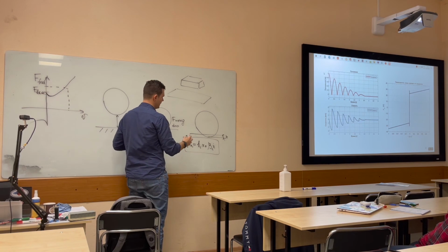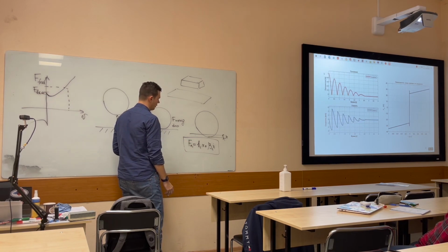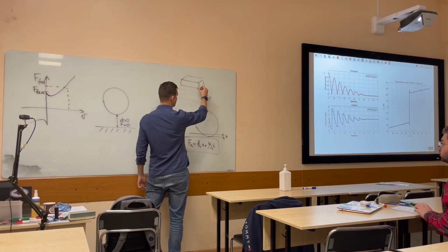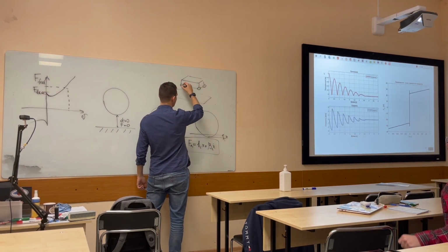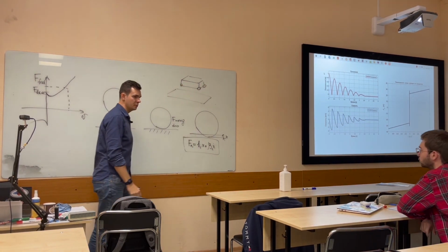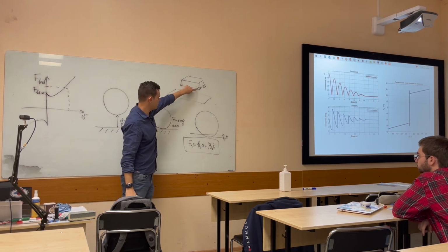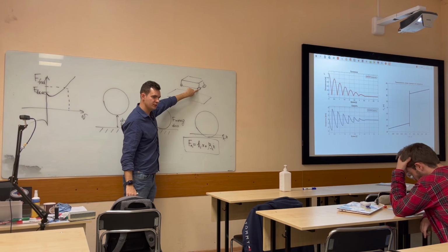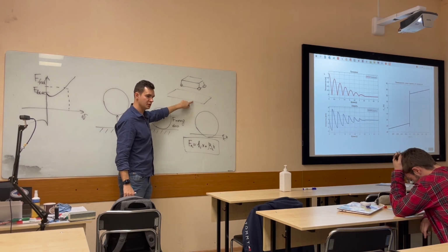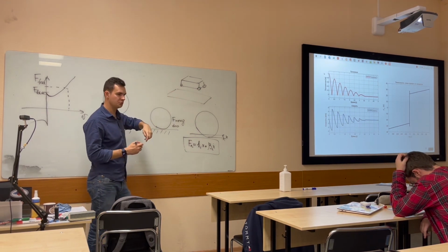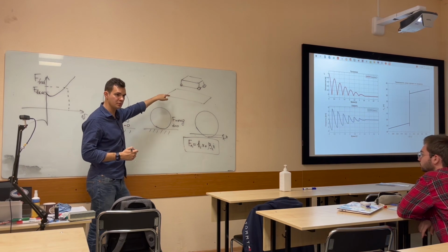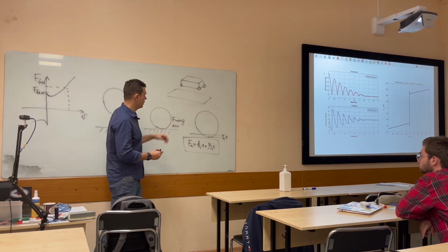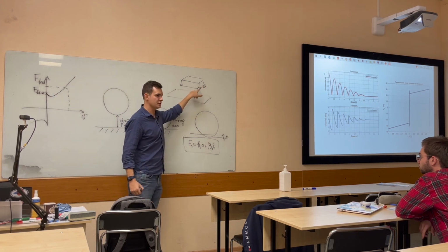You need to attach virtual spheres or maybe something else to the points of interest, and you're looking for the penetration of these virtual spheres with your plane, such that they do penetrate, but your real object does not. So you need to adjust the geometry of these virtual objects.